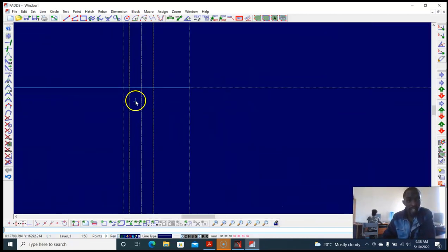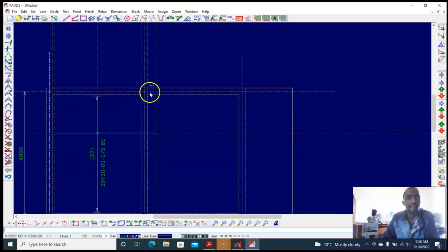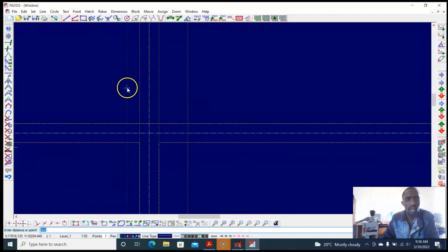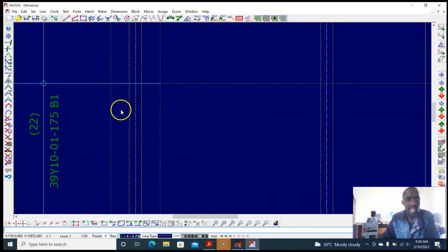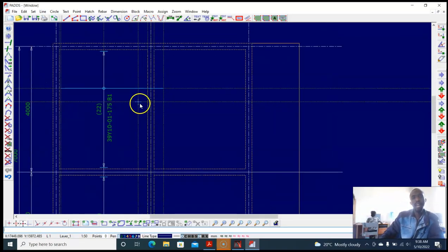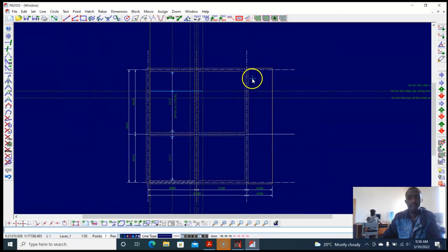In the same way, let's offset here ly lo 300, and I start, click there, lx. I start another rebar here up to there. But because of this beam, I need to provide a bottom for it. Let's extend again 300 that way, because 300 will be beyond the beam.